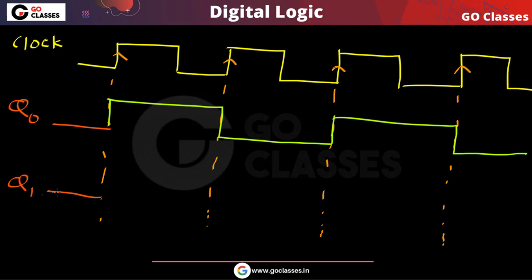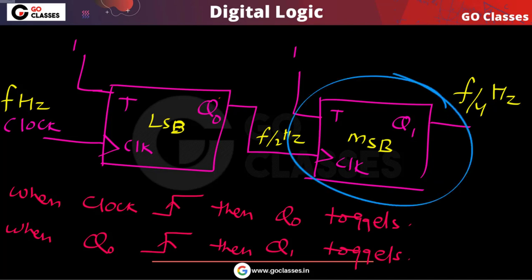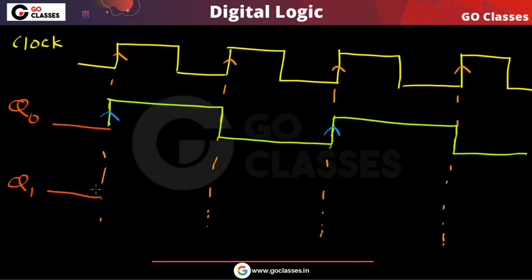Now what will happen to q1? Q1 will toggle with every rising edge of q0. Remember, these flip flops are positive edge triggered, and for this flip flop the clock is q0. So when q0 goes from 0 to 1, the output q1 will toggle, because the T input is 1. Whenever the T input is 1, the output toggles with every rising edge of the clock. So with every rising edge of q0, q1 will toggle.